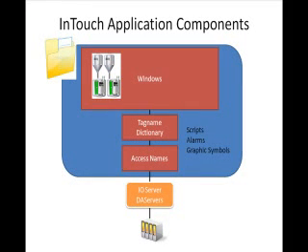So let's look at a general overview of InTouch. Let's assume you have some PLCs and you need to use InTouch to visualize and write to data in those PLCs. An essential piece in the communication link is the I/O server or data access server, which is really outside InTouch. It may be provided by WindowWare or a third-party vendor like Software Toolbox.